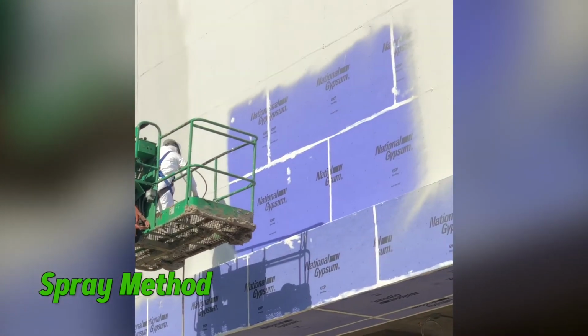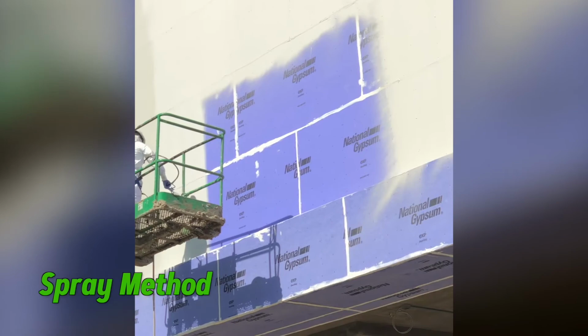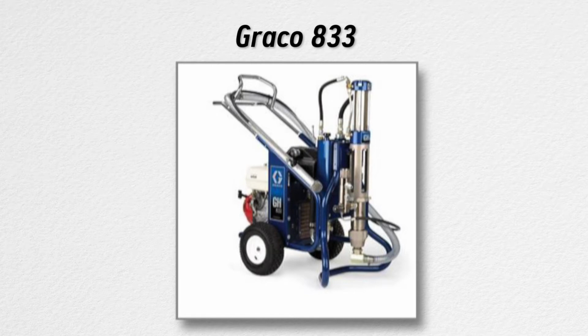Spray application will most commonly be used where there are large areas or large volumes of product to be applied at one time. There are many different equipment options that vary widely. Thin, less viscous products often can be applied with a smaller sprayer. As the viscosity increases and the volume of product increases, you would need a much larger roof coating machine. We use a fleet of Graco 833s. The machine is very durable, can run multiple guns at one time, and we have found very few coatings that